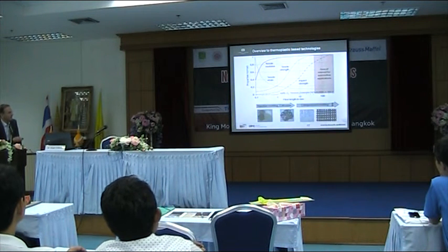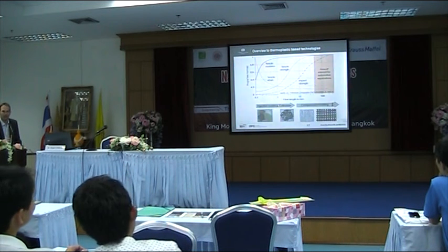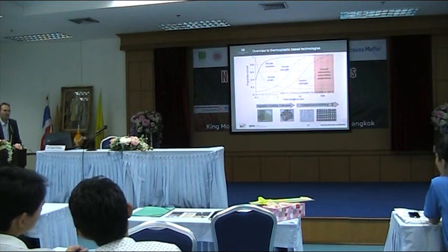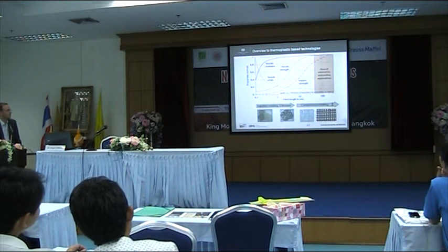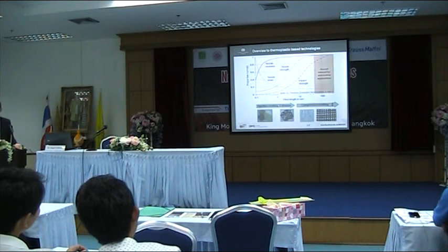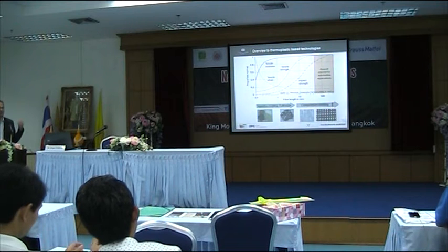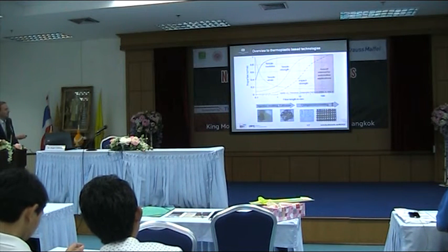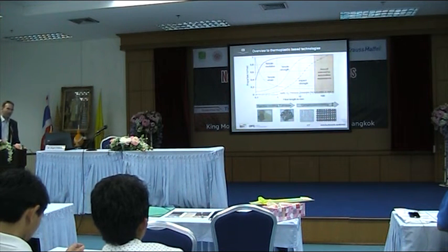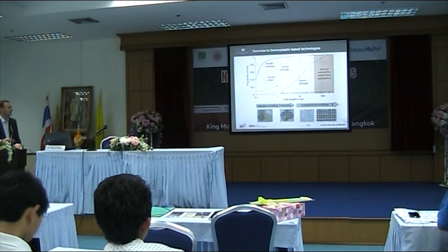The main dependence on longer fibers is the impact strength. So with longer fibers, you especially can increase the impact strength. When we look here at automotive applications, as you can imagine, impact is really interesting for automotive applications. If you have a crash, especially in the front end or in the back, it's interesting to get high impact strength. So there, endless fibers would make especially much sense. Tensile modulus, you cannot reach so much more anymore, also tensile strength, but especially tensile impact strength. Okay.